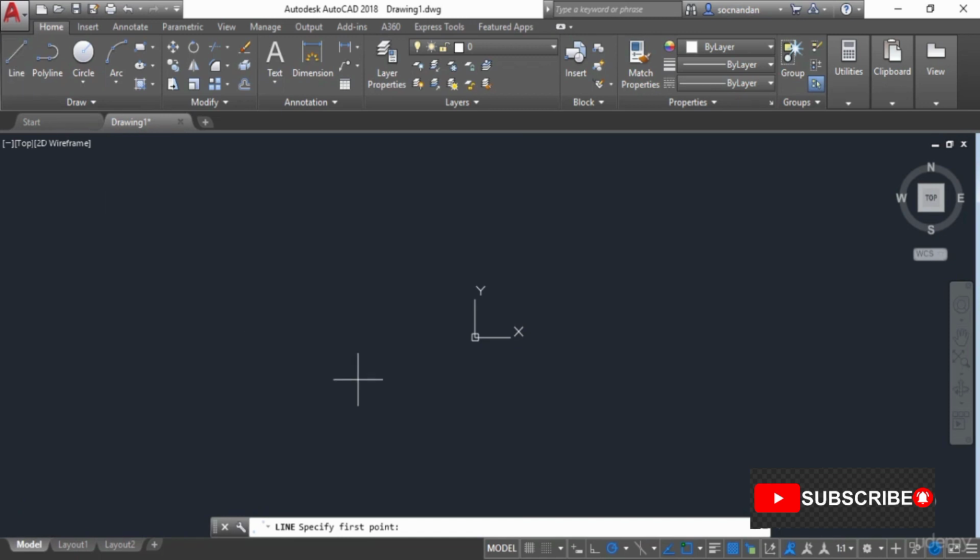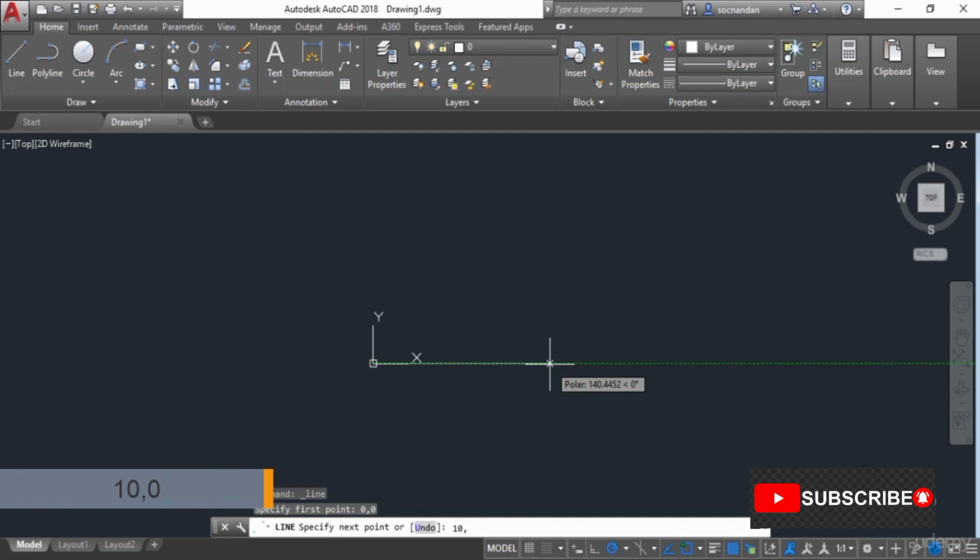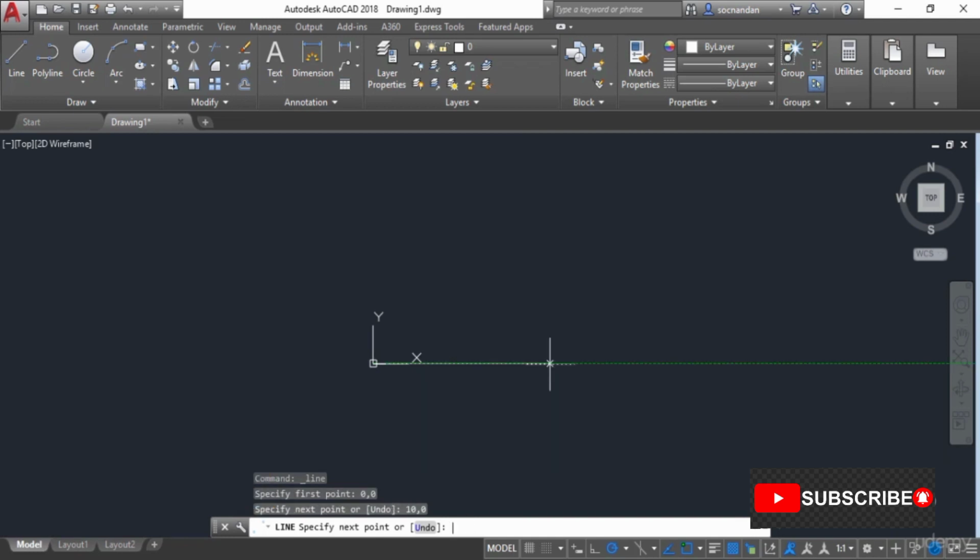We need to specify the first point as 0,0 and press enter. Now you'll notice that the cursor snaps automatically to the origin. Now we need to specify the second point, which will be somewhere at this place. Here we know that the length of the line should be 10, so the X value should be 10 and the Y value is 0, because its distance in the Y direction is completely 0. So I'll type 10,0, press enter, and here we have it, the line of length 10 units in this direction.